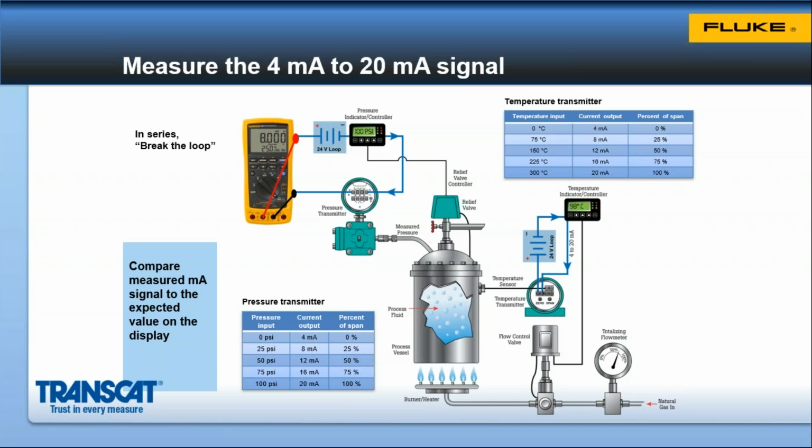Once the measurement is complete, then the technician has to put the loop back into autonomous operation. Once the test connections are removed from the meter and the process wiring is returned, then another conversation with the process operator to put the loop back into autonomous operation. So that takes a number of precautions and interactions between the operator and the technician as they're working in the field.